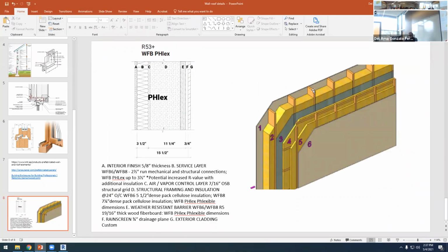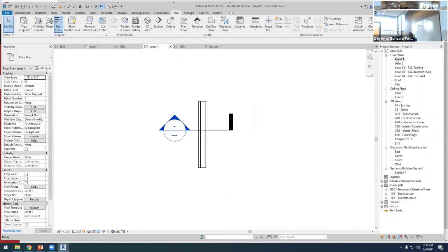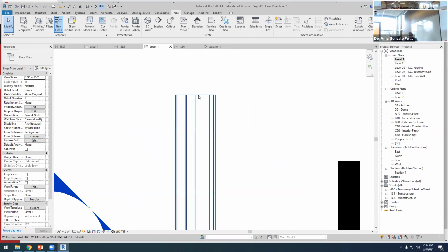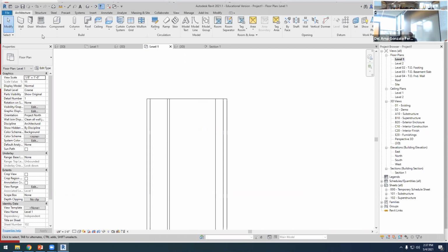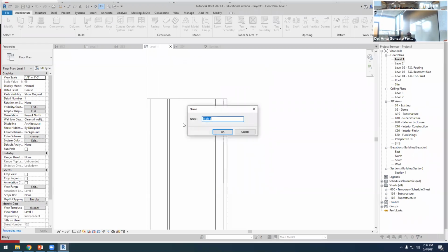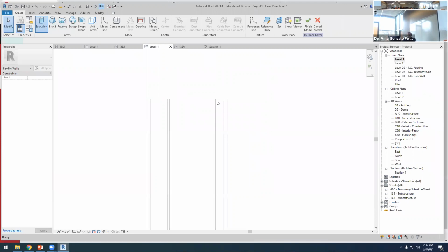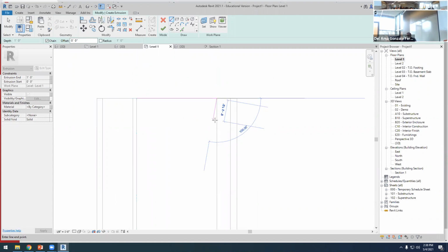The only thing you have to insert is the rafters. Okay, so somewhere we can work with level 1. And on level 1, we know that in this layer, that would be the cellulose. So here we can work with component, model in place, then walls, and we can work with extrusion. And with that extrusion, we have the rafter. It's a 2-inch rafter like this.